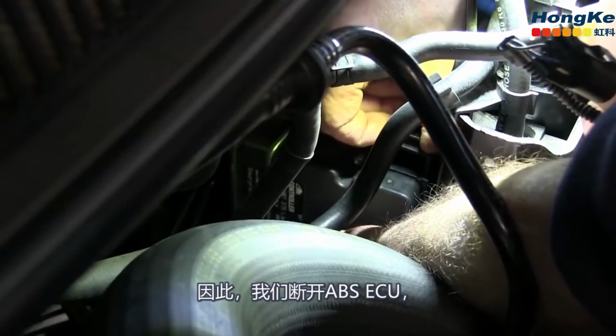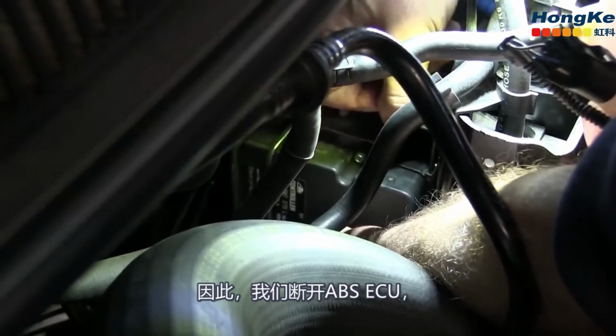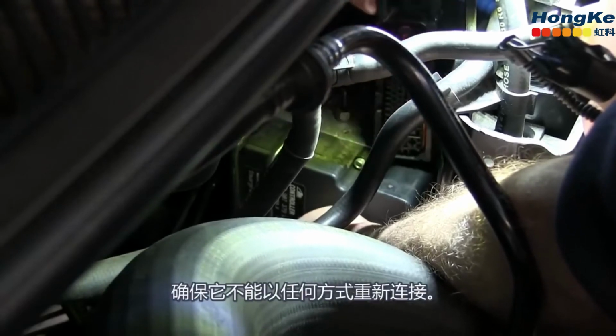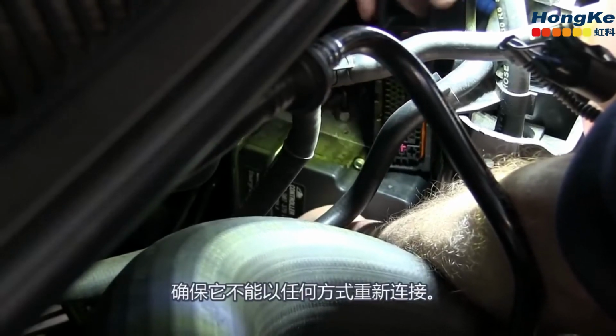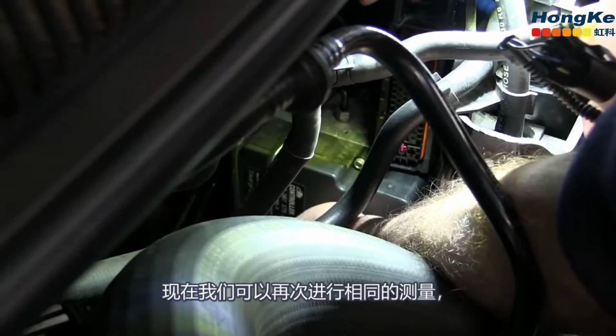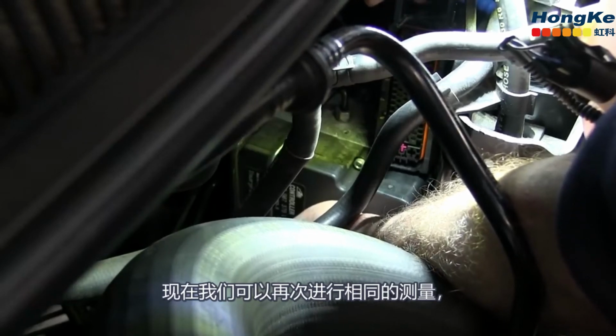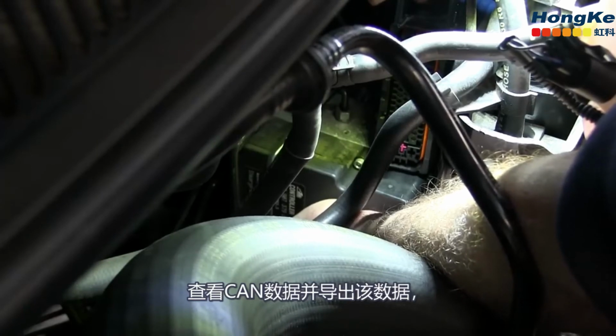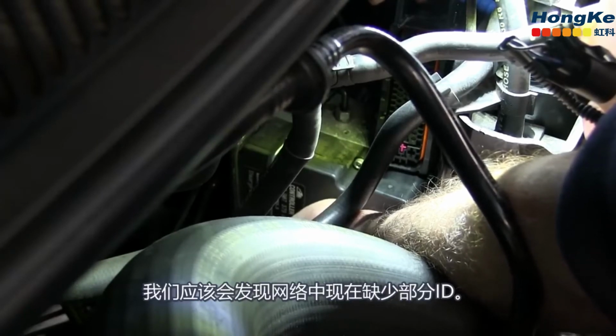So if we disconnect the ABS ECU, make sure that that cannot reconnect in any way. And now we can carry out the same measurements again, looking at the CAN data and export that data. And we should discover that there are missing IDs now from the network.